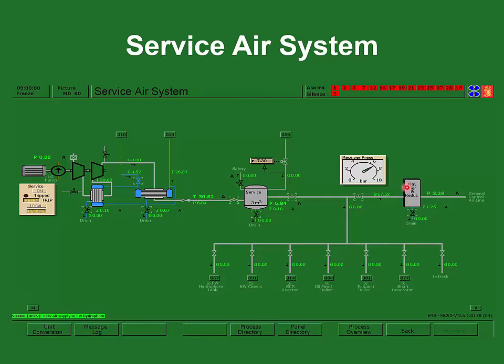On this too, you do have a filter dryer, and they're showing it on the general control air line. Typically today, by the way, you will have this both on the ship service and control air. Automatic drain traps are to be fitted at receivers and moisture separators. You've got to make sure you drain the water out of these systems and keep them drained. A lot of times today that's automatic, but automatic systems fail, so you do want to make sure that you keep an eye on it.